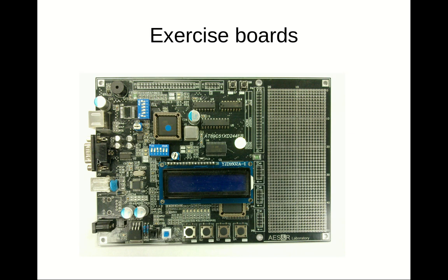Here you see also a connector, and this is the original RS232 serial bus connector. In fact, you see here these switches, 6 different switches, and there you have the possibility to choose between the USB connector and the serial bus connector to connect to the microprocessor. And this setting of these dip switches is the one that is necessary to connect via USB bus.